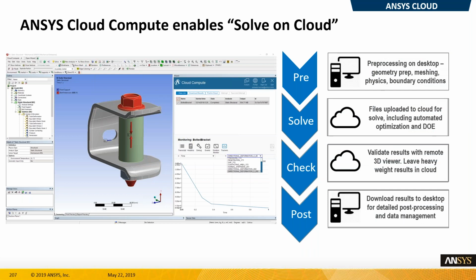Here you can't select which kind of CPU, and memory size is limited to what they call small, medium, and large. And especially the small one is 16 cores. The medium, as I have been told, is 32 cores, and the last one is 128 cores for the Mechanical version, at least. The small, medium, and large settings are different for the Fluent interface.